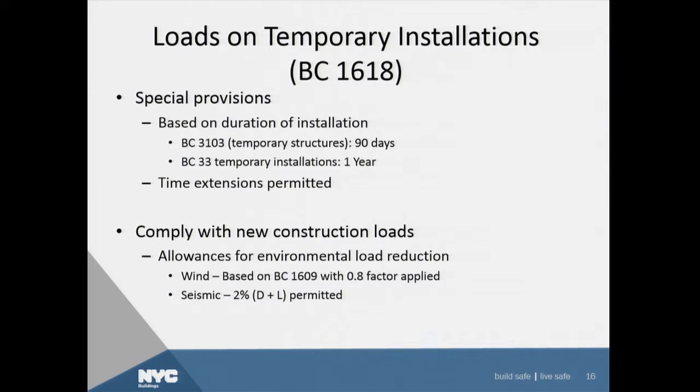Now, there are other environmental load allowances permitted in the text. So, for example, if something is only going to be installed in the summer months, let's say installed at Memorial Day and taken down Labor Day, and in the design professional's opinion, snow loading was not to be considered in the design, that's something that we would consider. So the text allows for something like that.